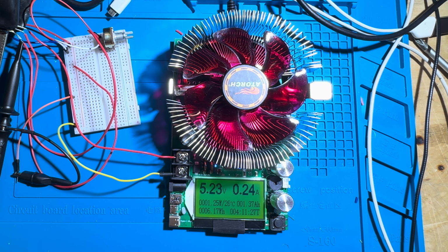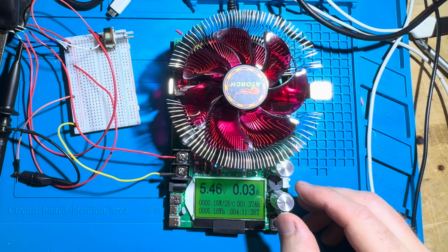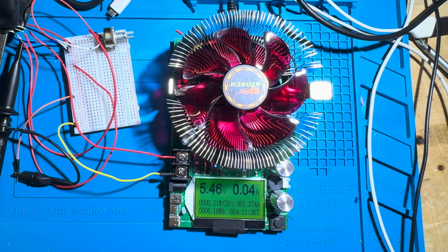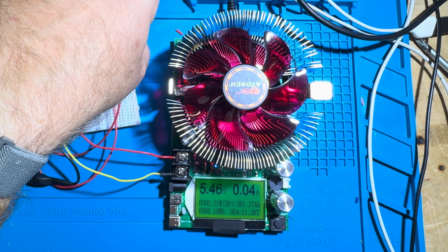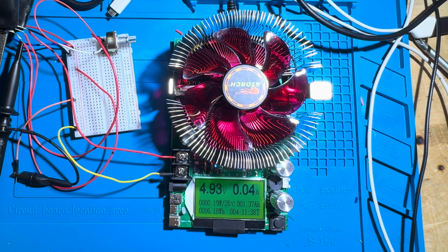One of the other things that we're going to notice about this is that very small changes in gate voltage result in large changes in the conductivity of the MOSFET. So when I go down to a very, very low amperage here, in order to target my 5 volts, I've got 8.72 volts across the gate.